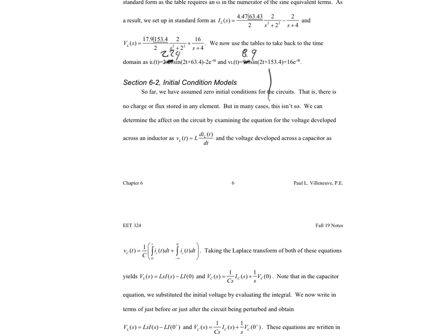And as we talked about in the previous video, the current in an inductor lags the voltage by 90 degrees. The voltage angle is 153. The current angle is 63. Bada boom, bada bing, you've got a 90-degree phase shift. That is indicated by ELI. So this works. So let's continue on.